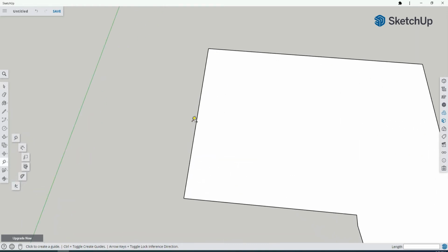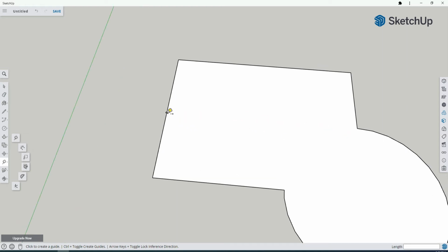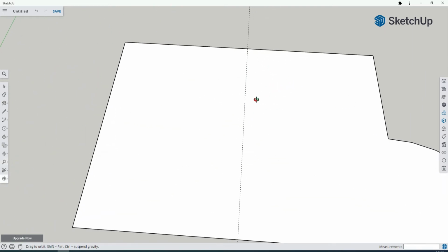And the tape measure is really interesting for a variety of reasons. So let's say I wanted to add a wall perfectly in the middle of this rectangle. So what I'm going to do is pull off of the side here, and I'm going to look for the midpoint, which is a location, you can see it's highlighting it there, that I can snap to that top wall. And now I've found the center point of that room and I can build off of it. So I know that interior walls are 4.5 inches, so that's going to be 2.25 inches in either direction.